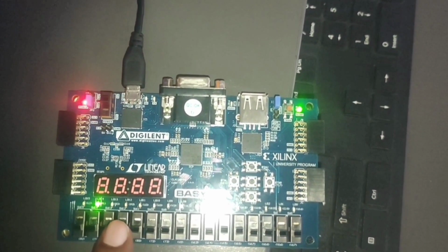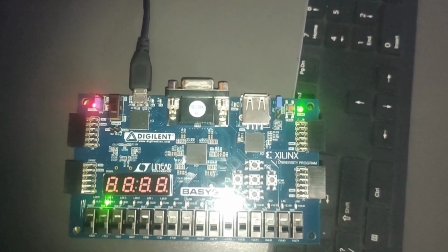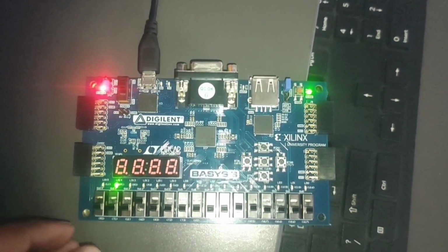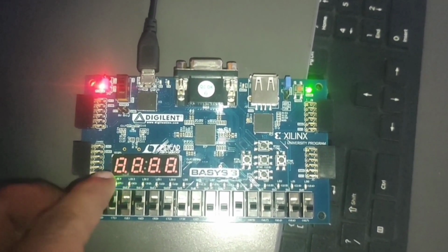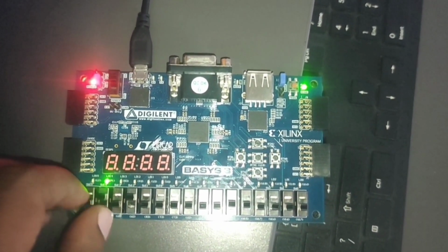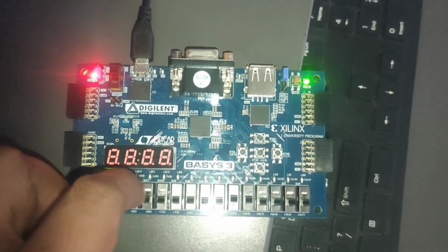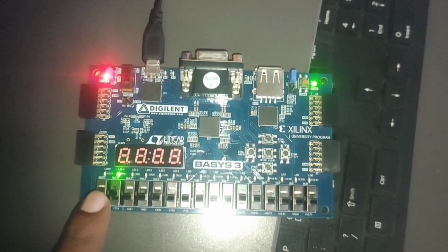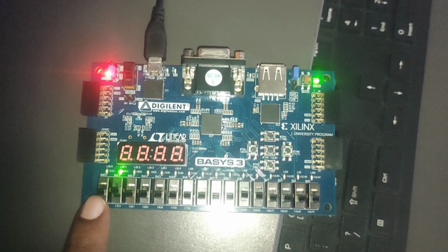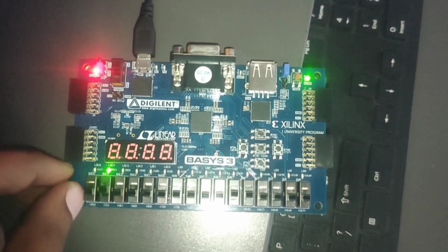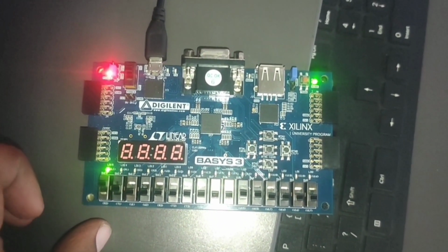Initially the reset pin is 0. We are going to make the reset pin 1. So if the reset pin is 1, whatever change I make in S and R, it will not be reflected in Q and Q bar. Okay, you can see this one, right? Whatever the change, that is not reflecting in the output. So I'm going to make the reset into 0 now, and yes, I'm going to make S as 1. So Q becomes 1 and Q bar becomes 0.